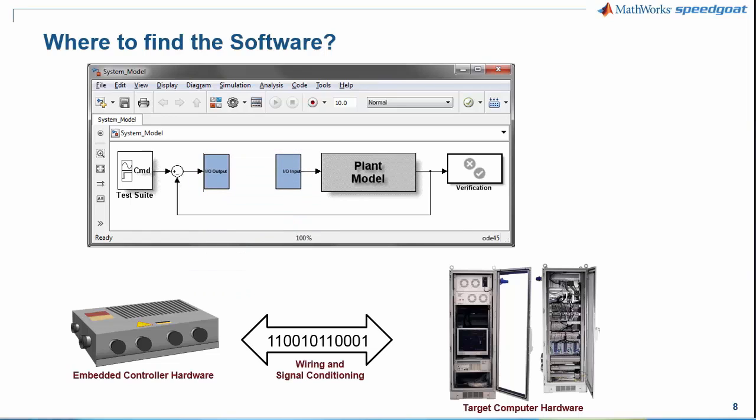As you can see on the model level, for HIL simulations, the controller model is being replaced with the corresponding I/O drivers. This represents the communication interface from HIL rack to embedded system. With the controller model deployed to the embedded hardware and the communication interface adapted to the hardware needs, it is time to deploy the rest of the test harness to the HIL system.